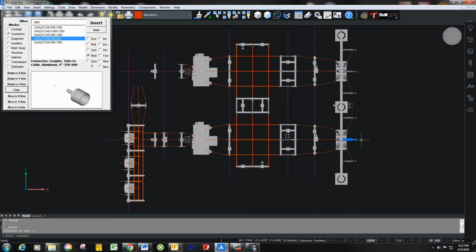It comes in dead ends, comes through a V-switch to an SF6 breaker, a circuit switcher, an isolating 161 kV isolating switch, cross bus, support structure, and then to the 161 to 12 kV transformer, then a 12 kV isolating switch, a meter structure, another support structure with a station service transformer. Then we have three outgoing breaker bays.